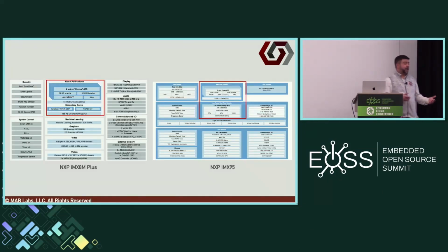So for example, now, if we look at an SoC that's relatively modern, and actually pretty new, we can see that we have multiple MCU cores or different types of cores and heterogeneous subsystems within a particular silicon itself. So you have multiple Cortex A cores, for example, on the NXP IMX8M+, in addition to a hard DSP and an ARM Cortex M device.